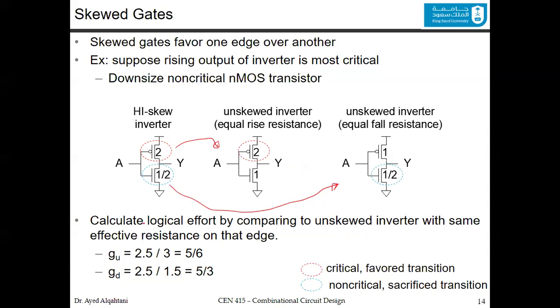How to do this? You now get the transition logical effort. You have only one input. And from the beginning up to this point, we always got the logical effort for the input. Now we get the logical effort for every transition, for the up and for the down, or basically for every network.